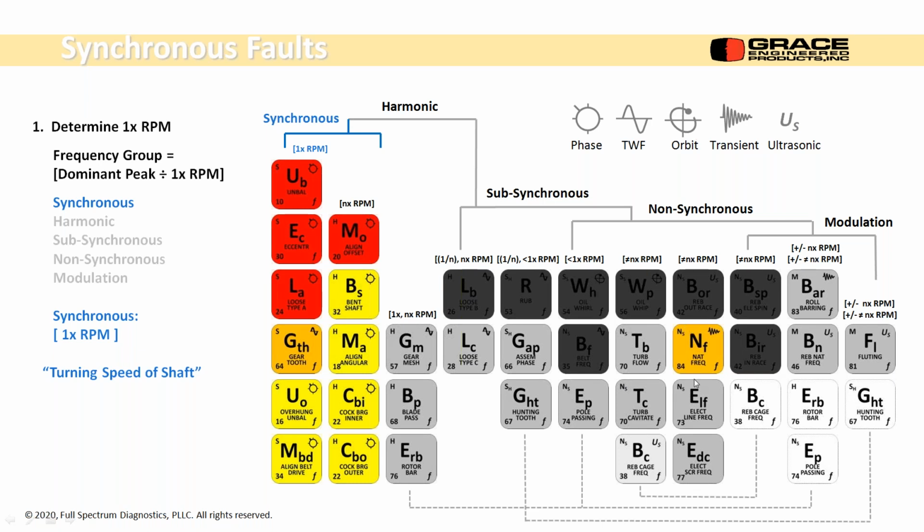And we have to throw in our little oddball. Natural frequencies can occur at any frequency. They're predominantly based on the mass and stiffness of the system that's vibrating. Okay, so if they get close to turning speed, you can amplify the response, but they're in every category. So we have to prove or disprove everything on here. So right now, synchronous problems, we got rid of all these other grayed out tiles, right? So we went from 35 problems down to 12.